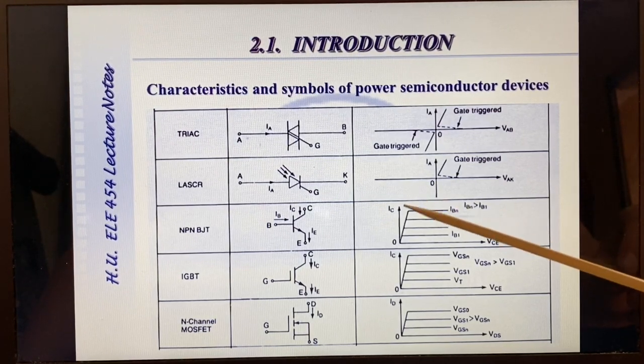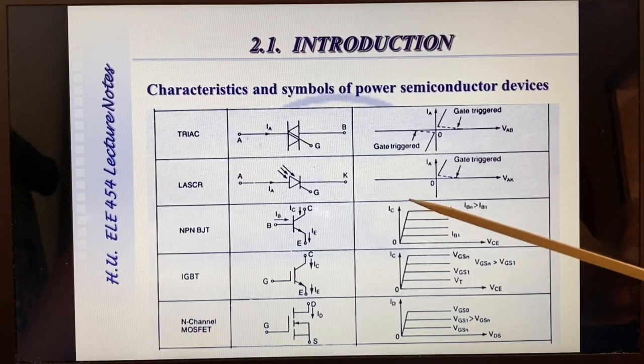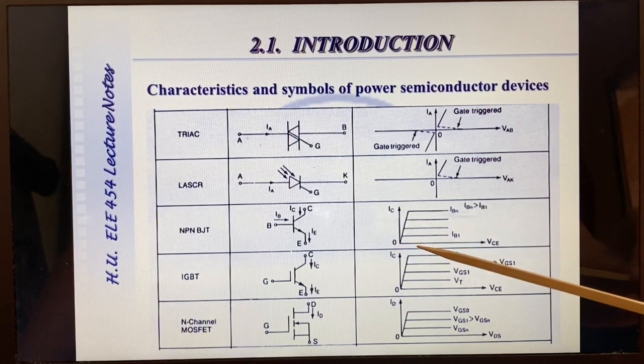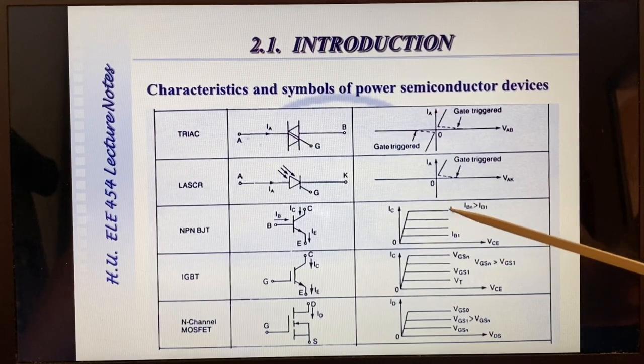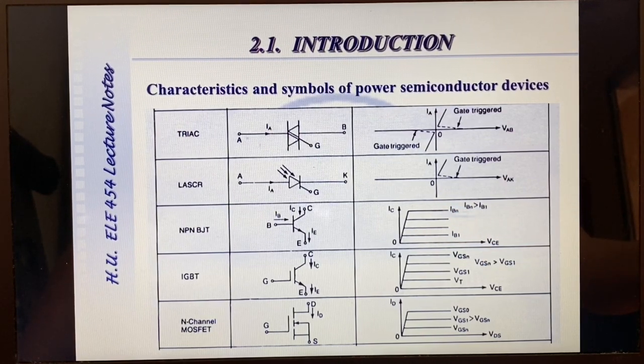So this is here the operating region in the on state and in the off state. So this part is not used in power converters, in power electronics, because of a very high power dissipation, lowering the efficiency and increasing the temperatures of the devices. So either fully on or fully off states of power semiconductors are used.